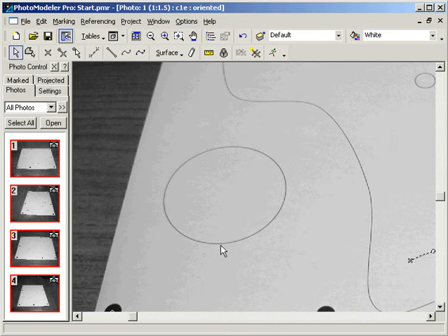Next, we will mark the closed curve. With a closed curve, you do not need to have a common starting point across your curves on the photos. We just start marking anywhere along the curve and mark points at regular intervals. We end the closed curve by clicking on the beginning point. This is how a closed curve is defined in PhotoModeler, when the first and last point are the same. When the curve closes, it changes the shape to take into account that the curve is closed. You may often find that closed curves will need to be adjusted after they are marked.